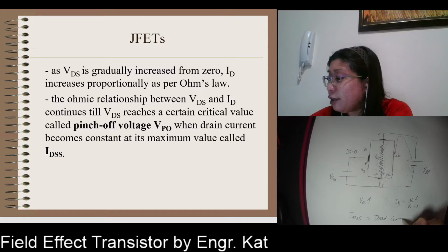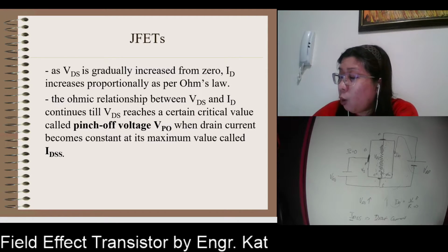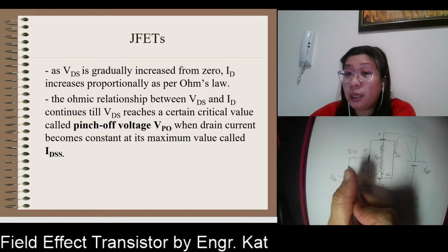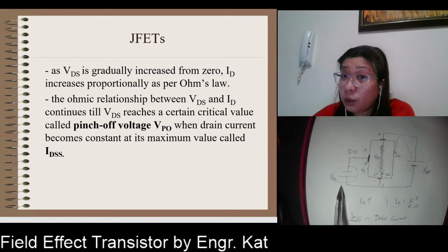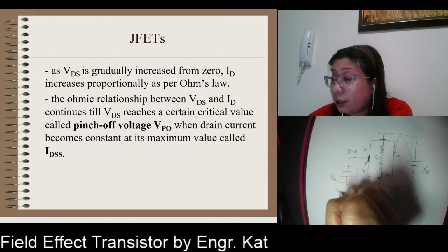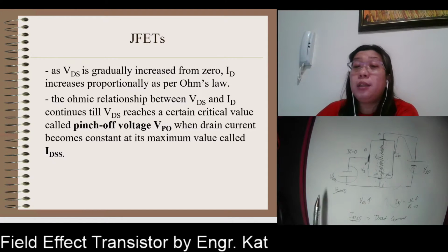This is the drain current. What is missing? IDSS. So the gate is missing. When the gate is shorted, so this is IDS, what is missing? The gate. How did we know that the gate is shorted? Because we said earlier that VGS is set to 0.